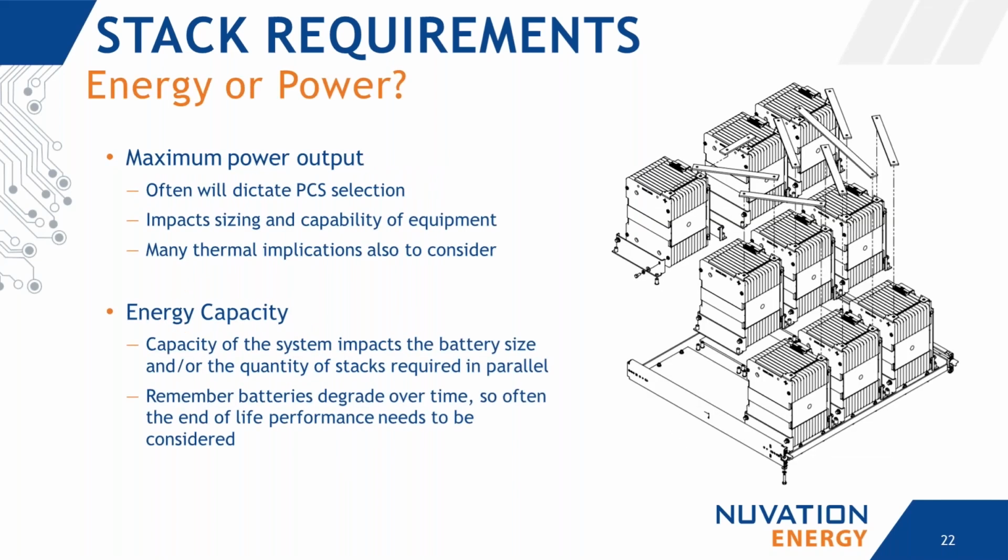Earlier, we mentioned a wide range of applications where we see energy storage used in the market. We won't break those applications down further, but in general, applications tend to fall into one of two categories, either a power or an energy application. What I mean here is, for an energy system, for example, we see systems are typically required to operate at or around half C or lower. Half C meaning a maximum output power equal to half the energy storage capacity.